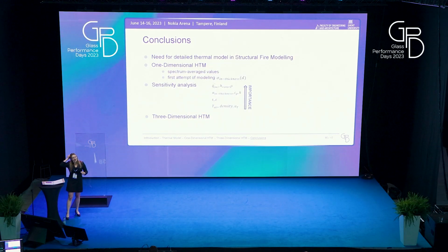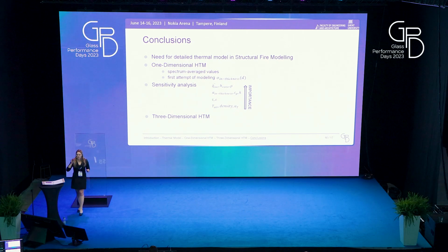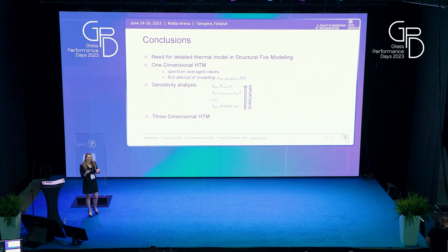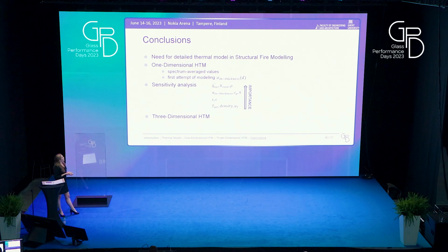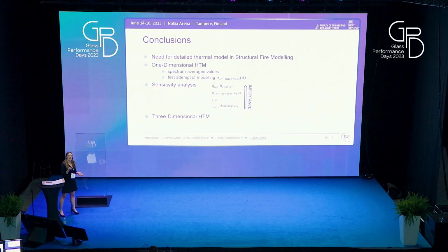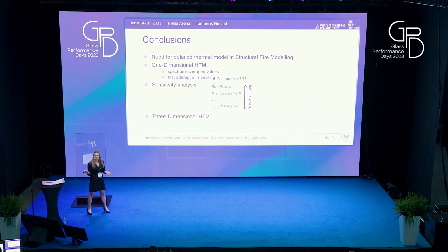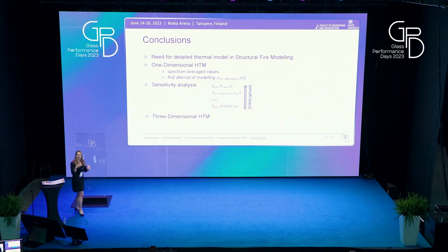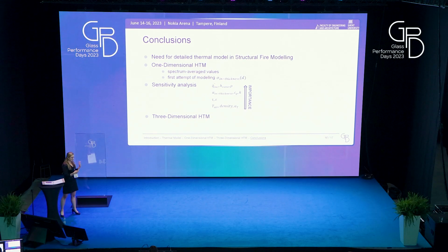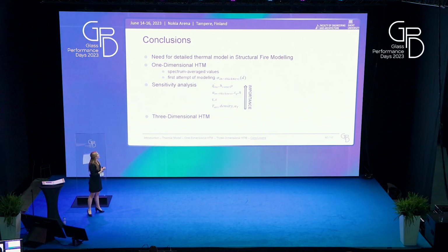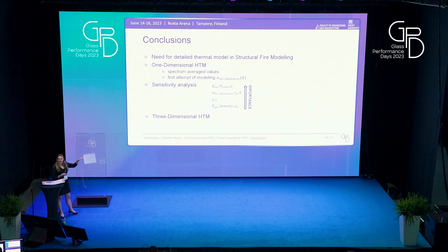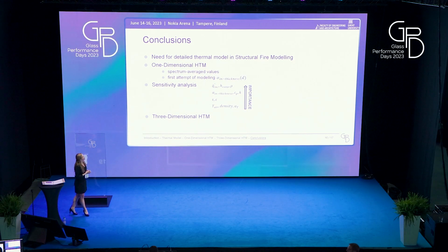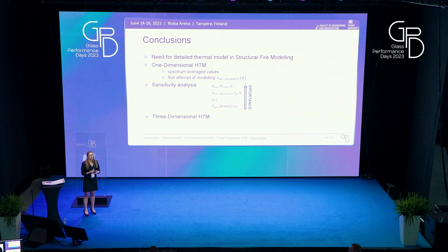OK, so that brings me to my last slide with the conclusions. Today, I showed you that there's a need for a detailed thermal model when we model glass in fire. We did a first approach with a 1-dimensional heat transfer model where we used the finite difference method, but we put some extra attention on the spectrum averaged values to implement the wavelength dependency when we talk about fire. We also did a first attempt on the in-thickness absorption. We then validated that heat transfer model with experiments, and we saw that it worked quite well and actually duplicated the reality.